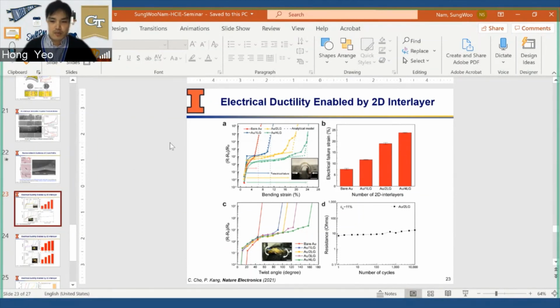In the first part of your talk, you talked about the Kirigami structure, and I saw that when stress is applied, it had this out-of-plane buckling to absorb that strain. I'm curious, for medical devices and others, we are stacking multiple layers for multi-sensor capabilities. Once you completely sandwich that Kirigami structure with additional layers, what's going to be the limitation of stretchability compared to that open out-of-plane buckling case?